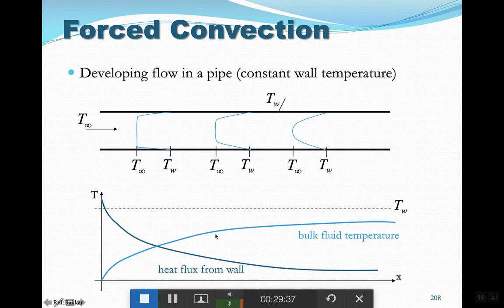In forced convection, one thing you have to remember, especially in places where you have long surfaces like a flat plate or pipes, is that you're going to create a heat transfer boundary layer, same as the flow boundary layer. Remember, you had the flow boundary layer and fully developed flow in terms of momentum. The exact definitions also come into effect for forced convection and temperature.